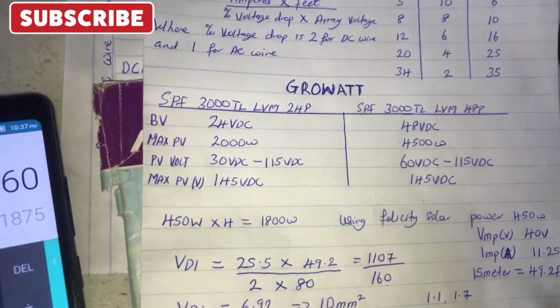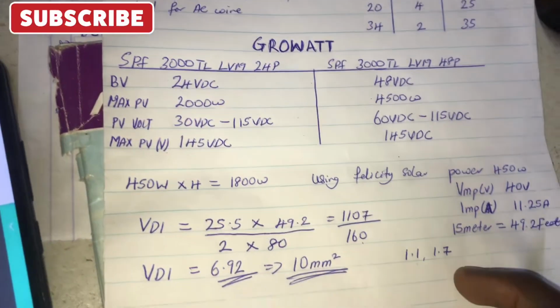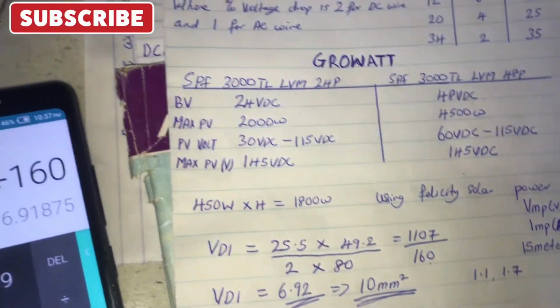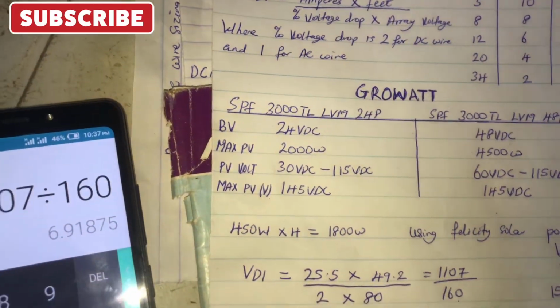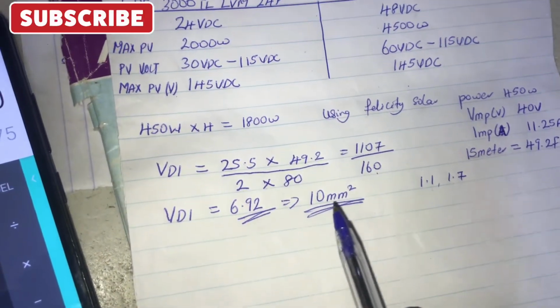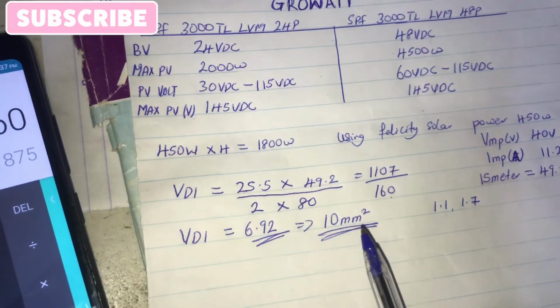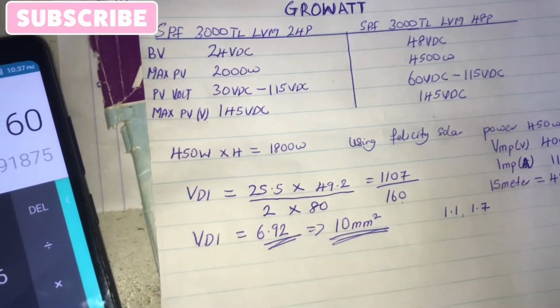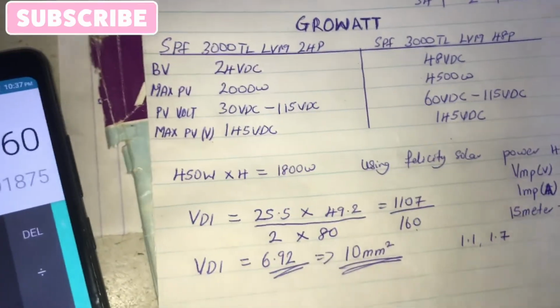But if you are not using an aluminum wire, I think this is just the best. If your distance is more than 15 meters, this value might be higher. So you have to be specific with the distance because of voltage drop and the rest.